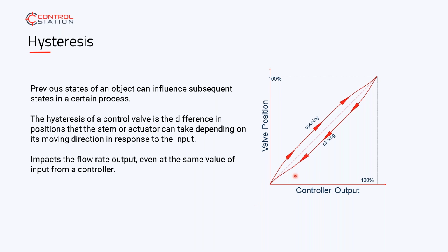Yeah, absolutely. The other one would be that spring actuators have a certain life and cycle on them. If they've spent their life compressed because of valve sizing potentially, it's lived in the fully compressed position on the spring. The spring performance is going to decay over time. It's one of those long-term scenarios. If this process has lived fully open or fully closed, or mostly open or mostly closed because of valve sizing, that's the kind of scenario that you could develop over time, even if the design and balance was correct. But Brad, well taken on that point.